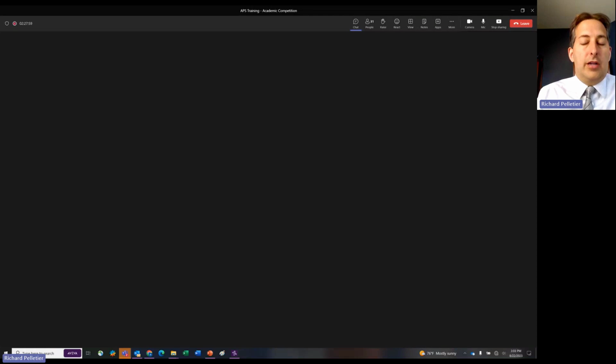You could work in some ways to do startup and shutdown, but there are very specific concerns when it comes to startup and shutdown in dynamic simulators, and the normal dynamic operation with the process model library and many of the other model libraries doesn't really do the full scale startup and shutdown. We do have a batch distillation library, which by its pure definition being a batch operation is going to have a definitive start and end. And that does start up and shut down for that specific process. But it's the only one where that is more all encompassing.